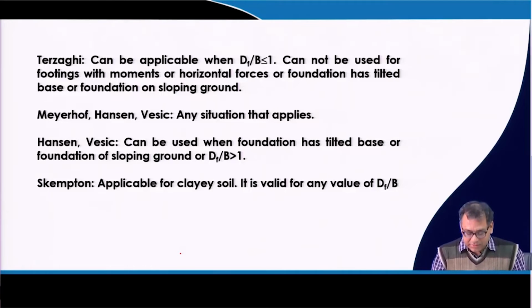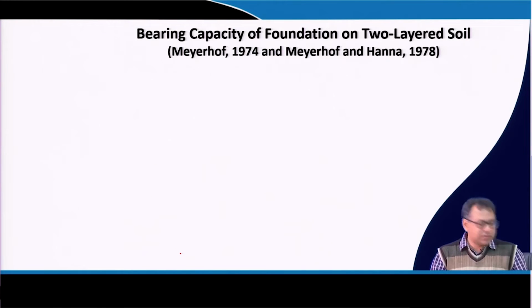Now the next topic that I will start is the bearing capacity of foundation on layered soil. In our foundation engineering course, generally we prefer to use the weighted average value for the layered soil case, and you can consider those properties for one particular layer, and then I will get the bearing capacity of the soil.